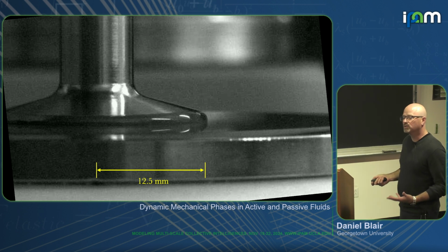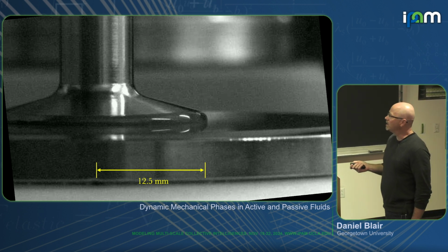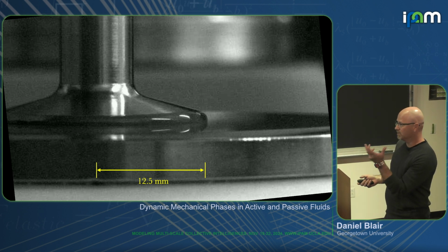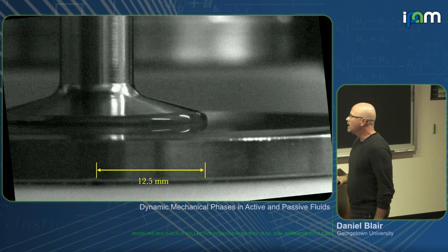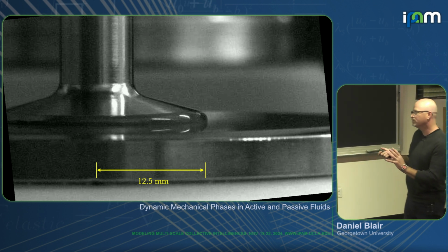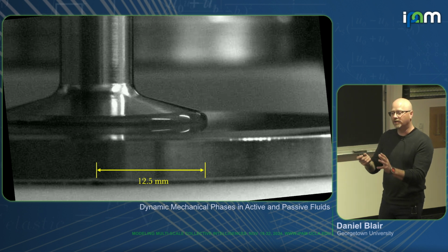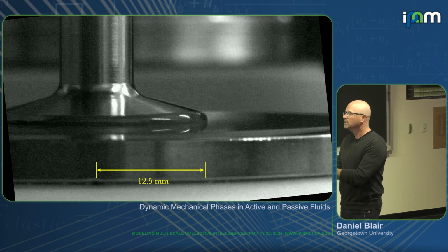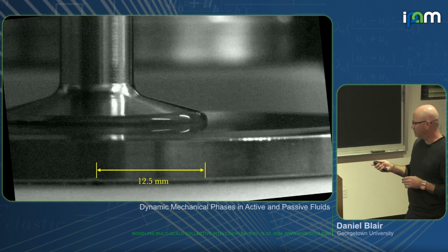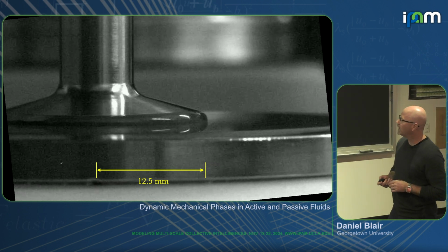It's basically mechanical spectroscopy. And I'm going to look at how this material responds to the force that I'm going to apply in a circular way. I always equate rheometers to if a Swiss watch and a blender got together and had a child, that's what a rheometer is. It's an extremely precise device for measuring forces.